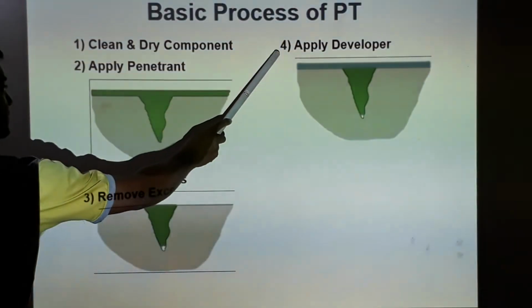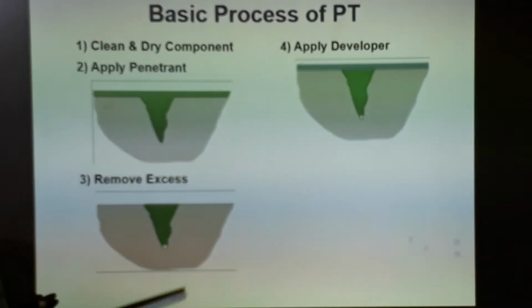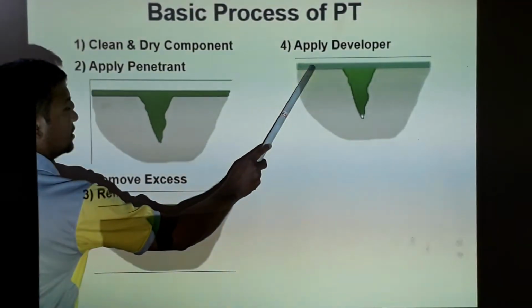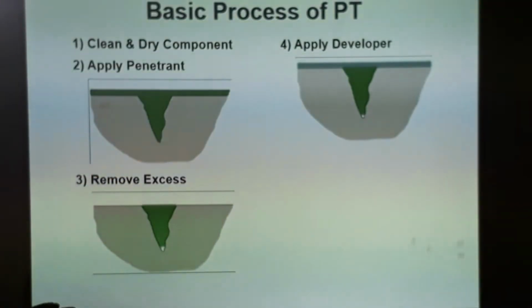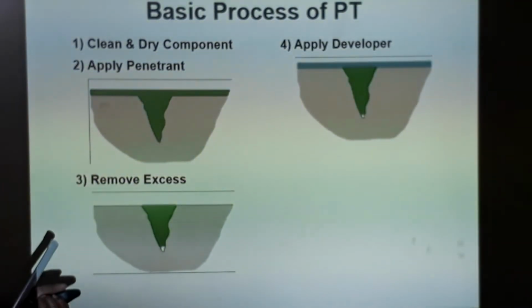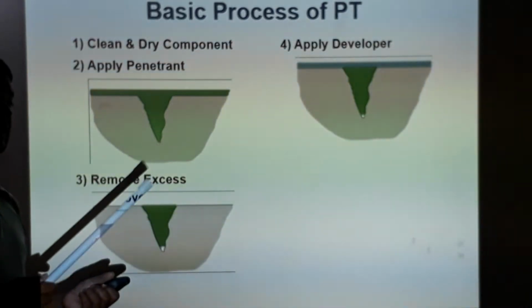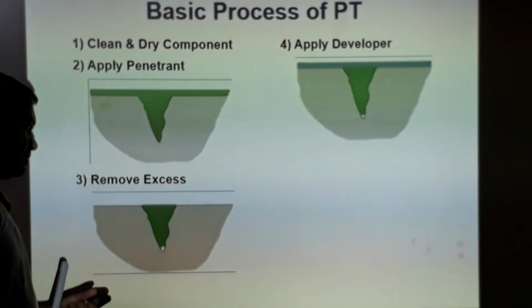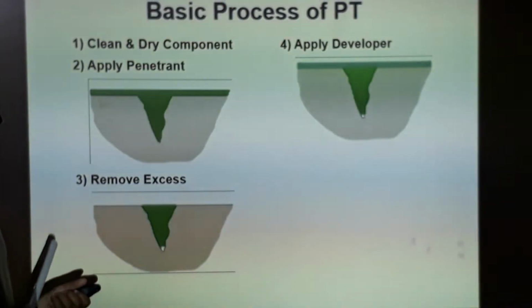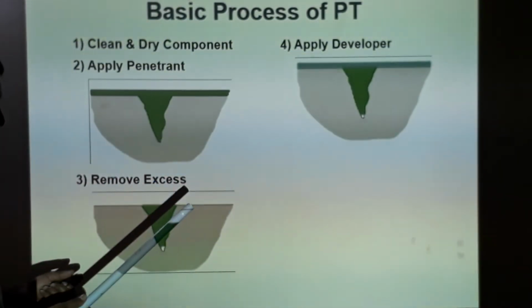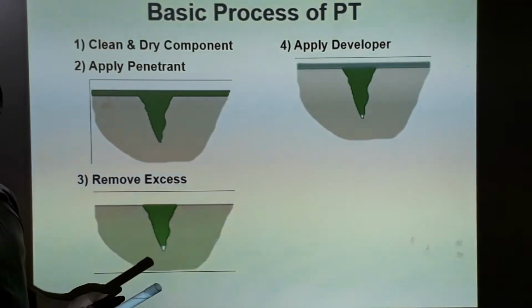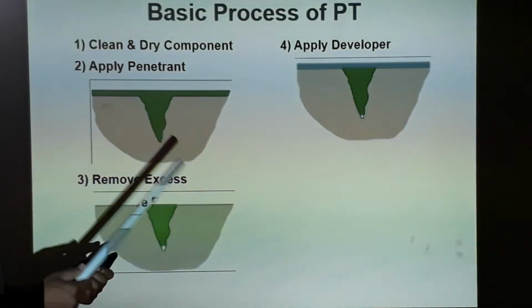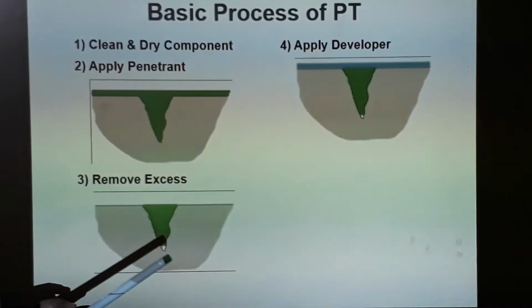Then apply the developer. This slight blue color stands for the developer. What kind of developer will you apply? What is the right process to apply the developer? What is the required time you need to apply the developer after the removal of excess penetrant? And what is the developing time, that we will discuss in the next slide. It depends upon the type of penetrant materials you are using.